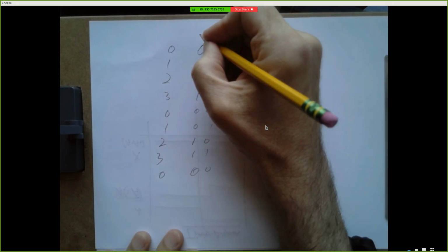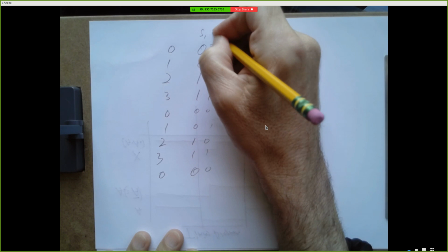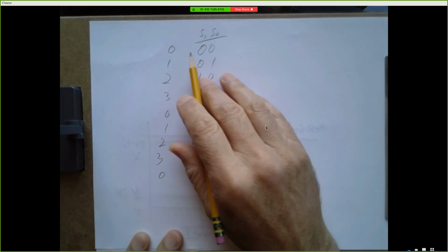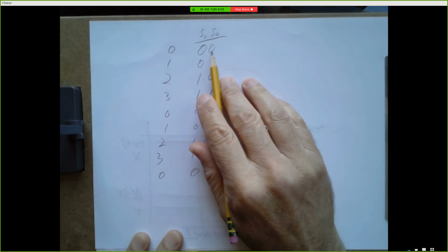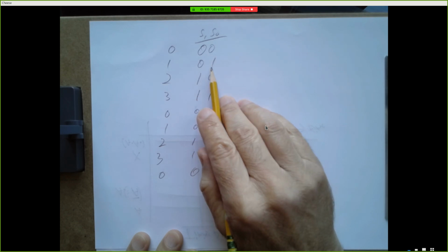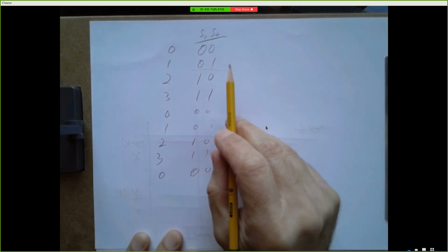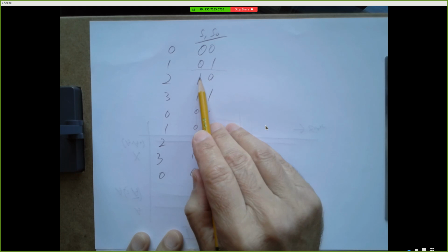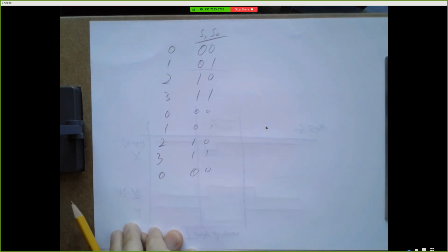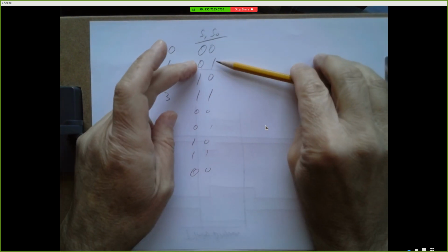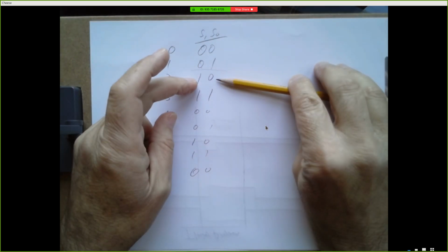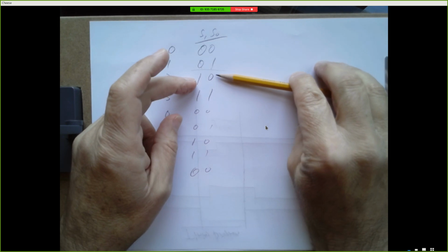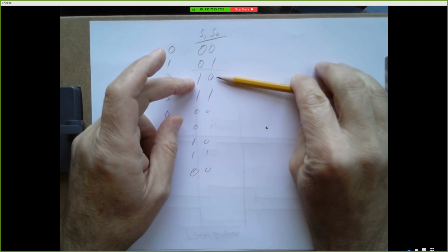So step 0 starts off at 0, 0. S0 is going to change from a 0 to a 1. That's our next step, 1. To get to step 2, two things need to happen. This needs to change from 1 to a 0. This needs to change from a 0 to a 1. Well, if they change at exactly the same moment, we go from 0, 1 to 1, 0. But it's not likely that they're both going to change at exactly the same moment.